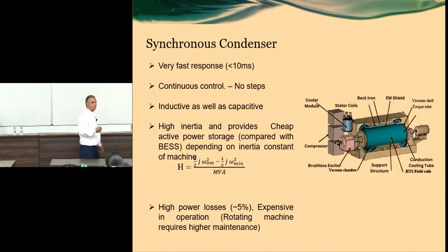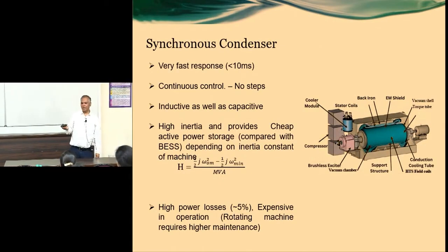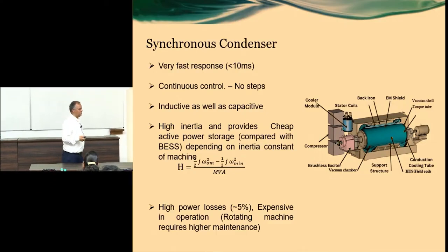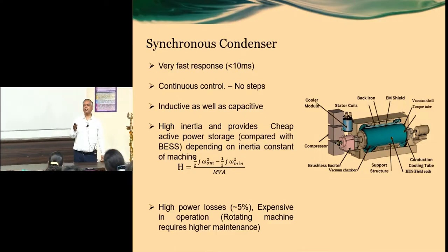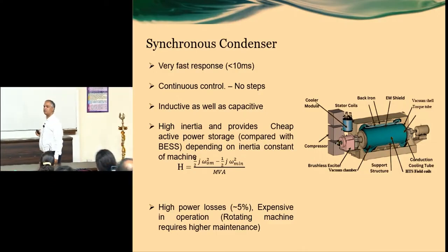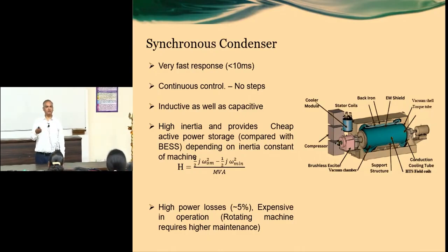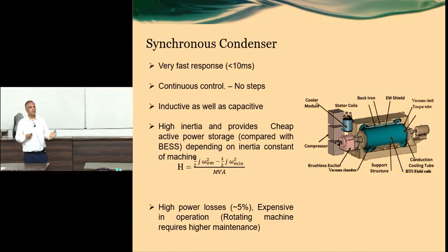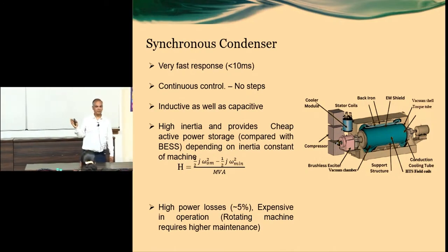Similarly, the synchronous condenser. Nowadays, because I am also an expert of Power Grid Corporation of India, I discussed that whole thing with them and delivered a special lecture to them also. Now the Ministry of Power is coming out with a solution: those thermal power plants which are on the verge of retiring, having already covered 25 to 35 years of their lifespan, the installed generation machine can be utilized as a synchronous condenser by removing its shaft.